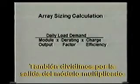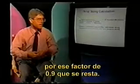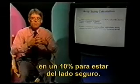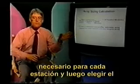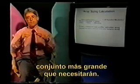Then we also divide by the module output multiplied by that derating factor of typically 0.9. In other words, we're reducing our module output by about 10% to be on the safe side. If you have a seasonal profile, you should calculate your array needed for each season and then choose the largest array that you're going to need.